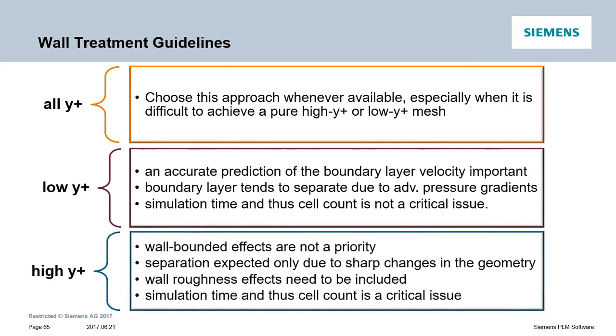Use a high y plus approach when wall bounded effects are not a priority or separation is expected only due to sharp changes in the geometry, and simulation time and the cell count are a critical issue.